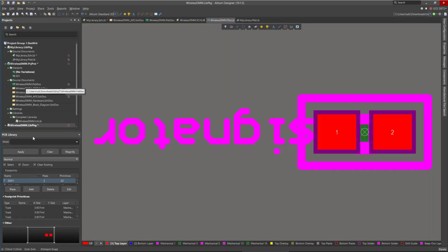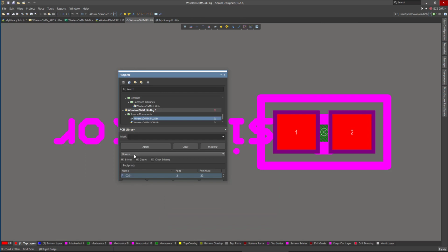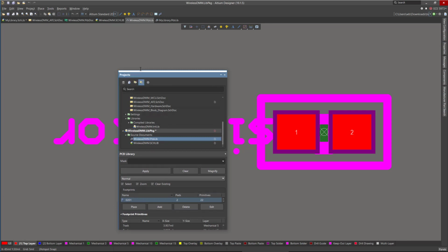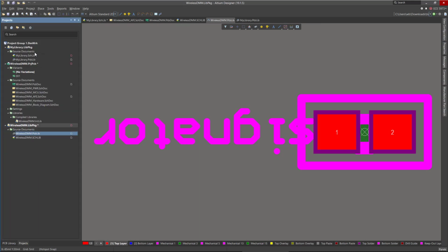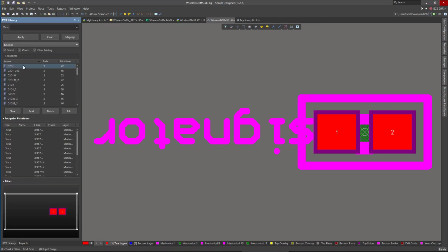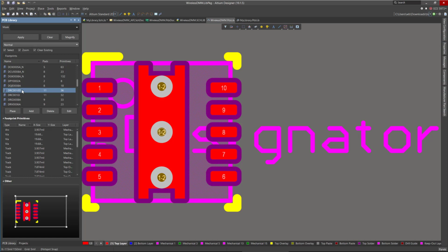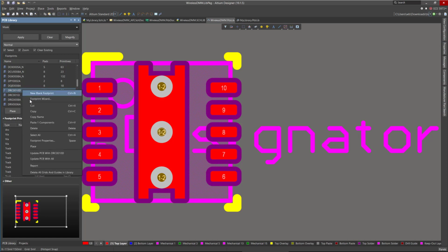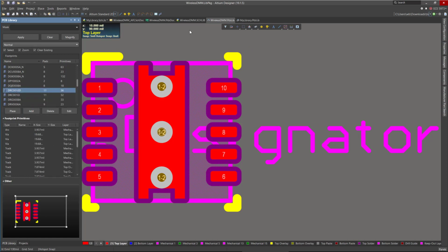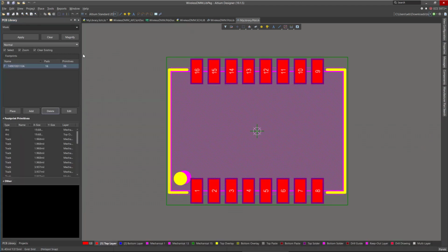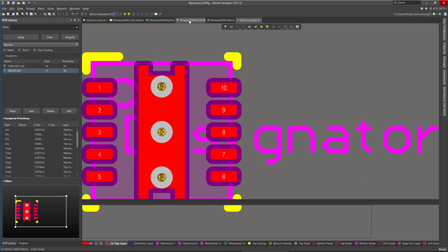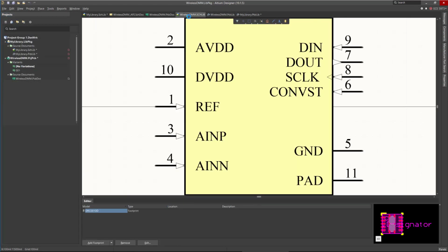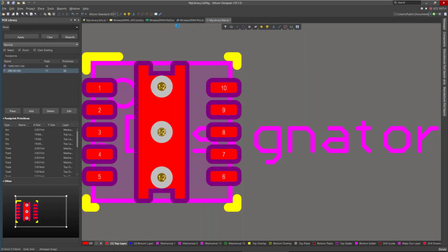and try to find, okay, PCB library, project, PCB library, SPR, this is the footprint, copy, and you go to your footprint library, paste, it's in here now. Let's close this library. We are done. We copied the components we want.